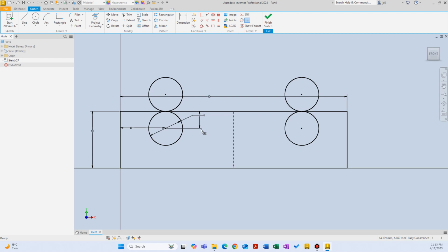Now everything updates accordingly. And that's why in the sketch mode, when we use rectangular patterns, circular patterns, or mirrors, if we can, we achieve symmetry, and we accomplish the desired geometry in a short time with fewer clicks. Everything stays fully defined. And if we have to go back and update anything, it takes less time to update everything, and you are much more in control of the design you are working on. So these are the patterns: rectangular pattern, circular pattern, and mirror pattern. And that covers the sections that we have to talk about with the sketch mode.